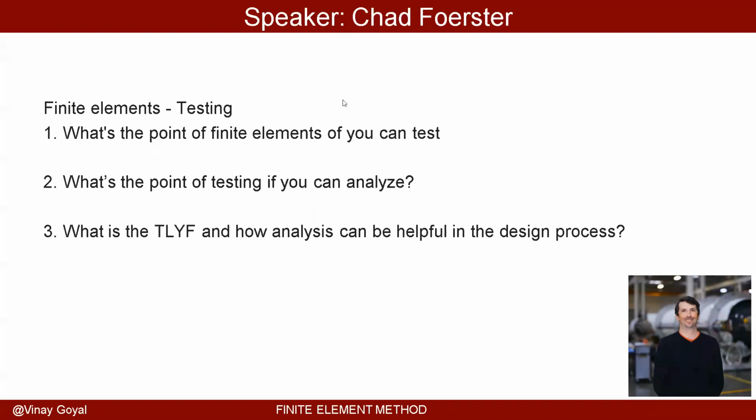That's the last thing. What is TLF? Test like you fly. And you really want to make sure your boundary conditions are as flight-like as possible. That would be the stiffness of your interface structures for the test stand. That could be thermal, but you want to make sure you're covered for your key driving shear and moments, which is just a free body diagram. Make sure you're covered.